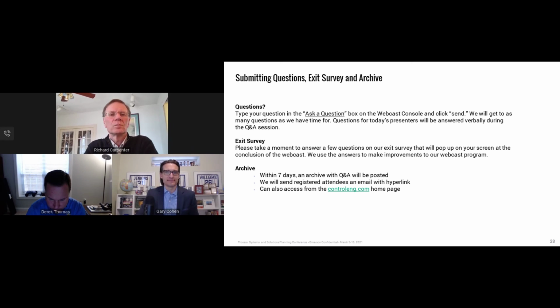Great. Our next question here is, what are the differences between edge devices and other data acquisition techniques? The data acquisition is sort of a general term, and an edge device has a data acquisition technique built into it. So I would say a data acquisition technique is a component of an edge device. What differentiates the edge device is, for example, data routing. The ability to connect something in on one protocol and without any programming or any additional scripting or anything, you can route that data to another place.